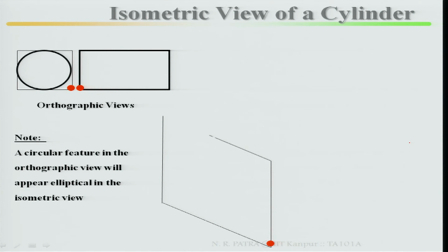Draw the isometric box, then mark your four centers, then by means of the four-center method, which I have already explained in the second class, you can go and brush up on how to draw an ellipse by means of the four-center method.